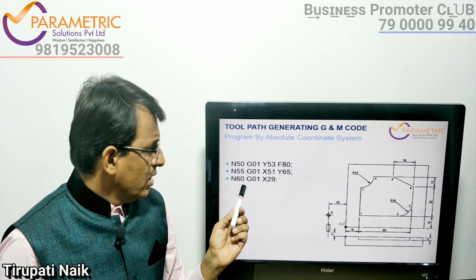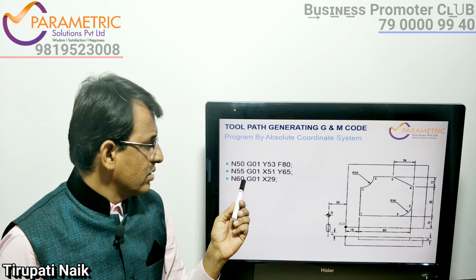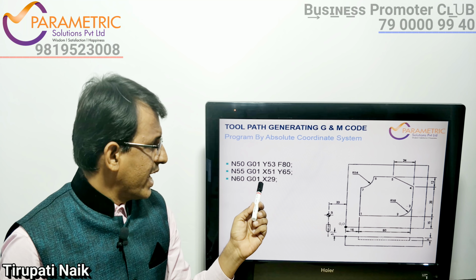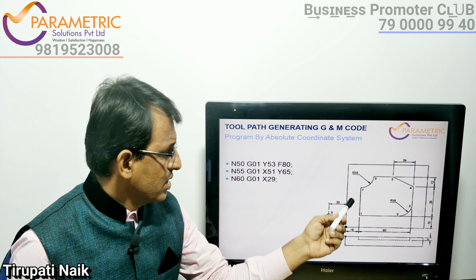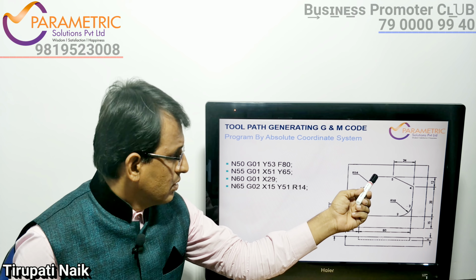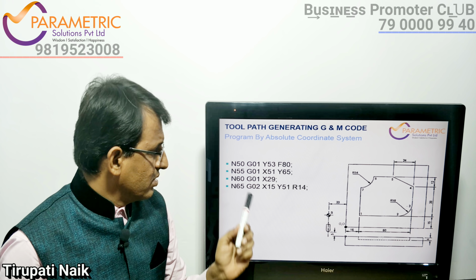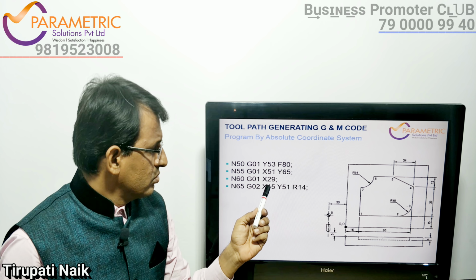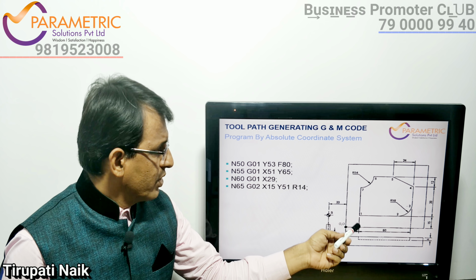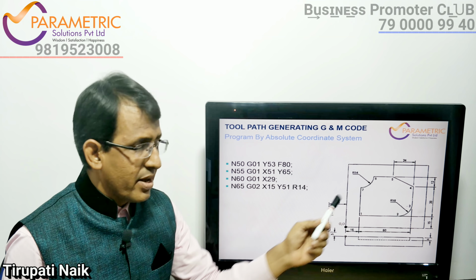Then the next step, sixth point, is N60, G01, linear interpolation, that is a straight cut with X29 mm, that is 15 plus 14 mm. Then from here again the clockwise circular interpolation, that is G02, X15, this distance is 15 mm, and from here to this distance is Y51, and radius is 14 mm.